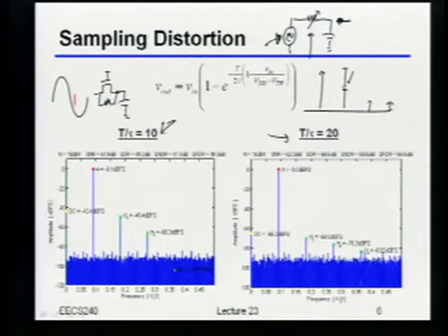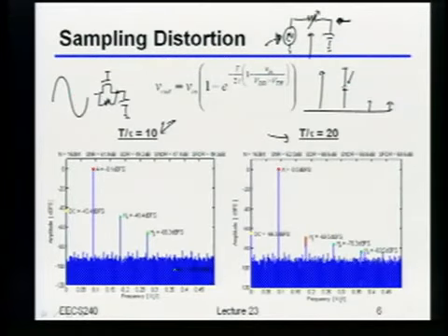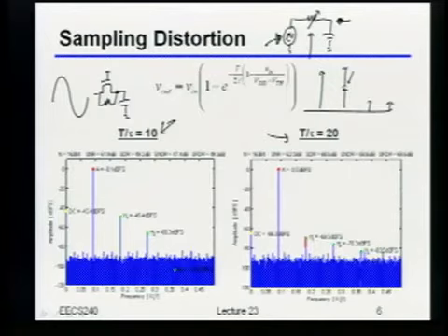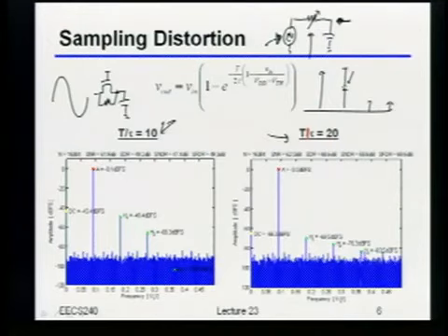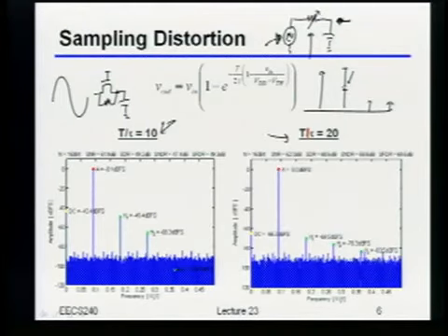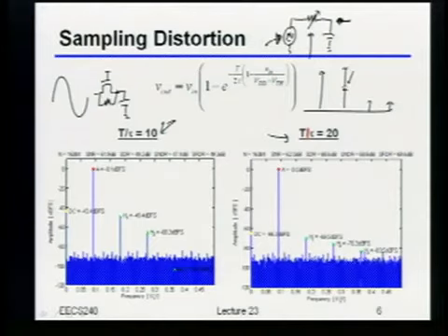So this is actually bad news again, because this says that if you want to get a certain resolution, you basically have to upsize your switches sufficiently to get a certain bandwidth, or to get much, much higher than the bandwidth you might have nominally expected based on that linear settling calculation we had done earlier. Okay? So again, that's bad news because pretty quickly you may even find that no matter how large you make the switch, you can't actually get the settling bandwidth or the settling resolution and speed that you wanted.